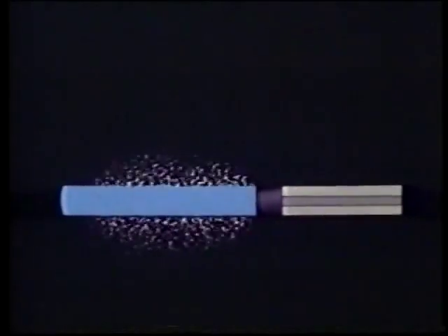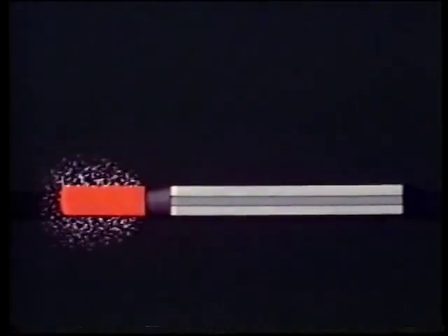The simplest type of cycle is the Carnot cycle, which employs only reversible changes. Compression is in two stages. The first stage of compression is isothermal. That is, energy transfer by heating occurs at constant temperature. The next stage of compression is adiabatic. No thermal energy transfer. The fixed mass of gas is now fully compressed. Expansion also occurs in two stages. First, isothermal. That is, thermal energy transfer with no temperature change. And finally, adiabatic expansion to bring the gas back to its original state.